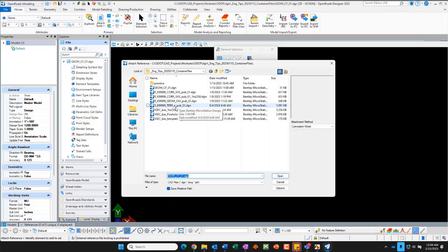The difference is in how you attach it. If you're attaching to a terrain container file, you're going to need to specify that you want to turn on live nesting so that you can see the actual published work. To turn on live nesting, you can do it after you make the reference attachment, or you can change your attachment method to interactive and do it on the dialog as you are making the reference attachment.